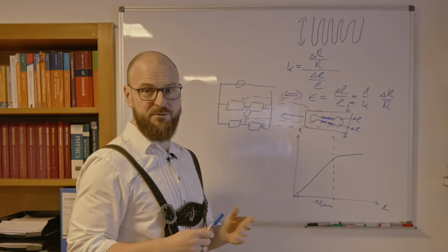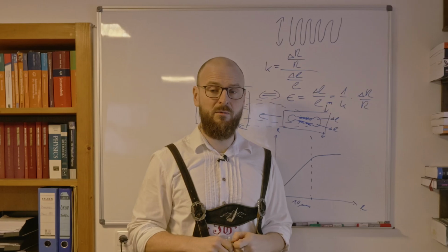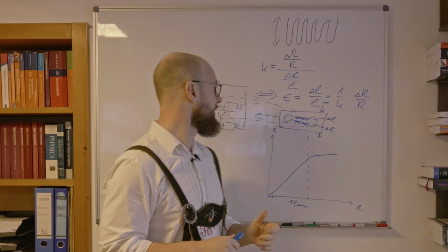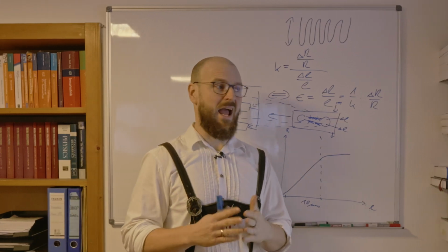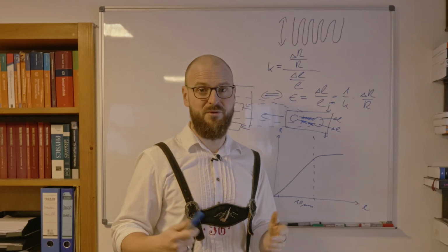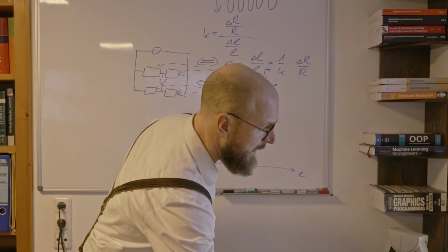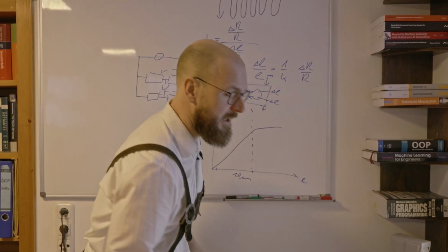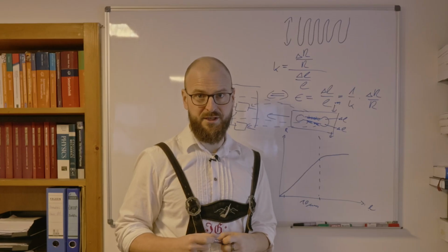Talking about those measurement bridges, temperature changes were always something which has to be respected when measuring resistances, because any material out there would or will change its resistance due to the temperature. Also, strain gauges will do so, but for sure we can compensate for that temperature change.